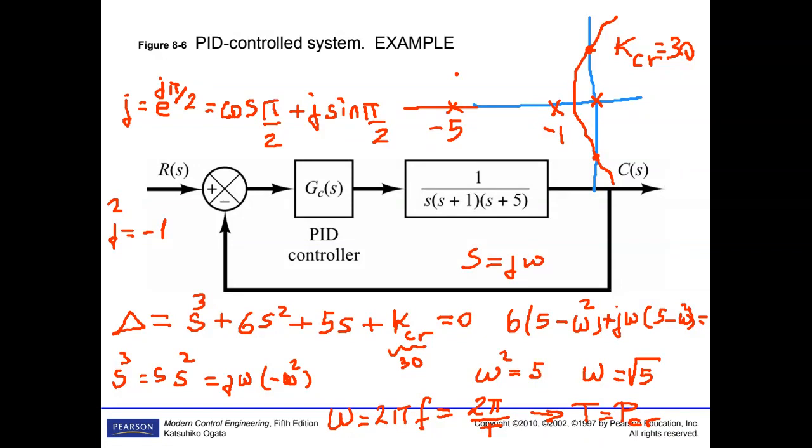Wait a while. Okay, the first one is your magnitude. The second one is your phase angle. All right, this is your Bode diagram. See, very easy. Just define your numerator, denominator, your bode. In the parentheses, you define your numerator and denominator again. Okay, let's do another one.